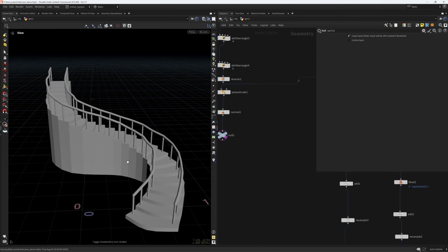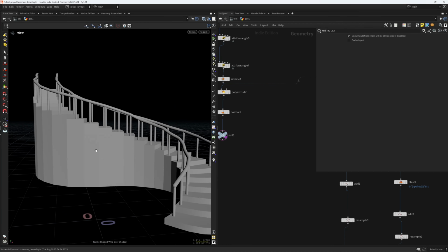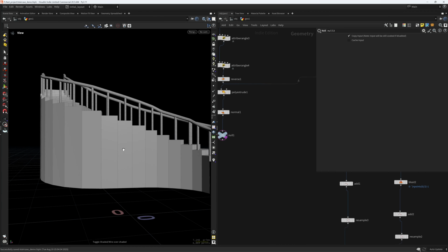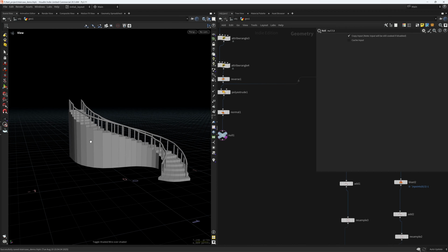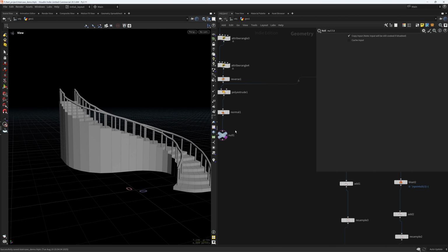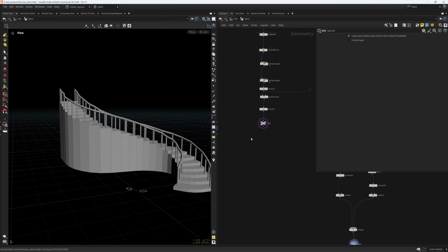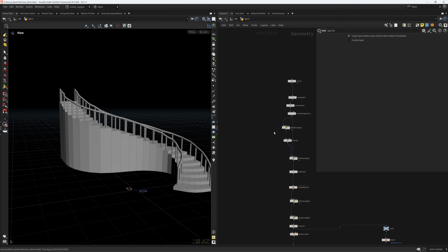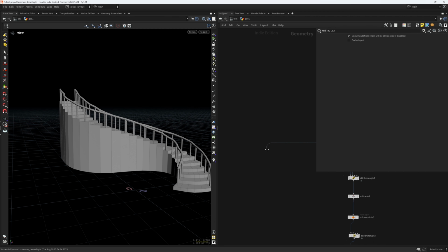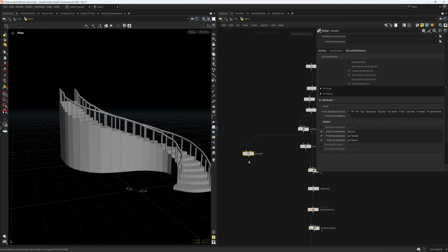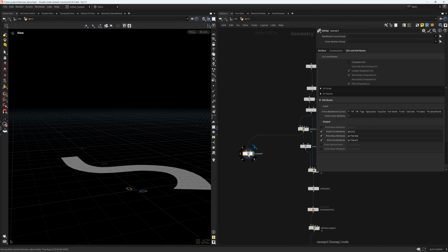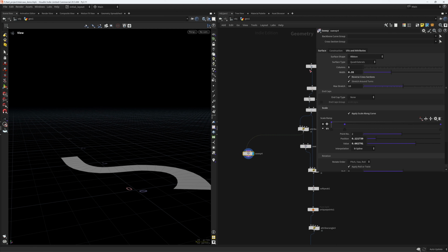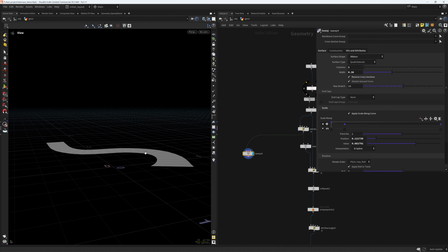So if we look at the normals of our geometry, we definitely can see this faceting effect, which is not ideal, so we need to rebuild part of the geometry in here and only keep the stairs. At least was the way I found it worked better. So for that, after this wrangle in here, where we manipulate the normals, I'm gonna create yet another sweep. And this time I'm gonna just remove all the columns and just increase a little bit the thickness, so 2.036.